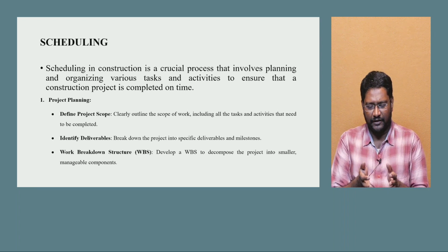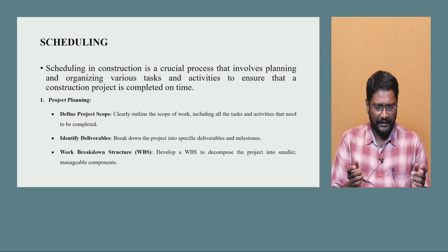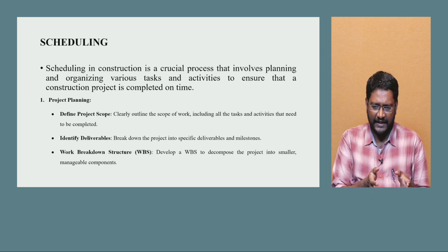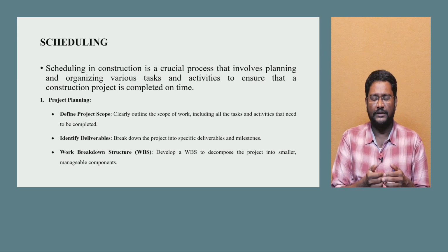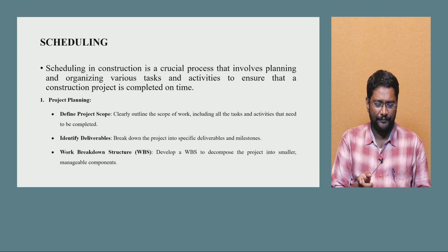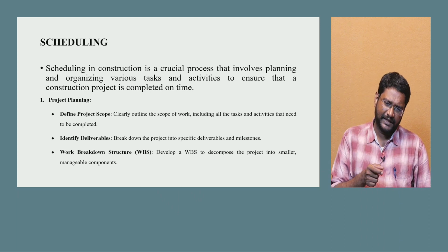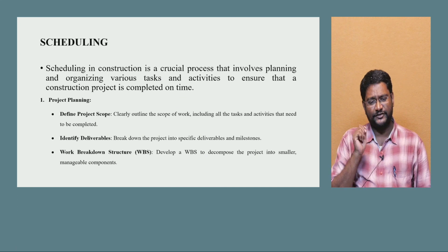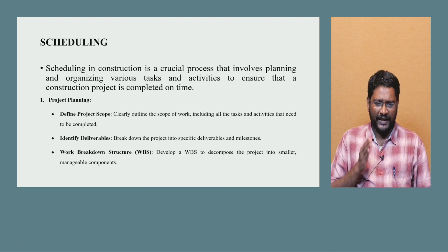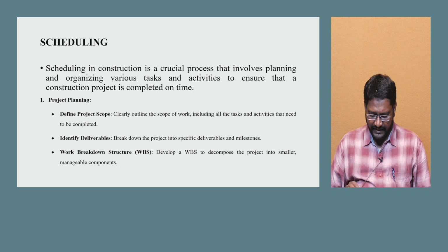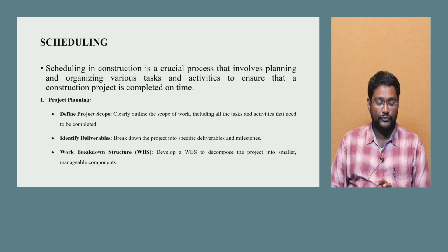Next, we have to connect with the pile cap. That will be the second breakdown. The third breakdown will be connecting the wall, that means a deep wall which connects all the piles together. So like that you have to break your work into smaller pieces that should be manageable and should be completed on time. Then only the scheduling and planning will be executed properly on the site.